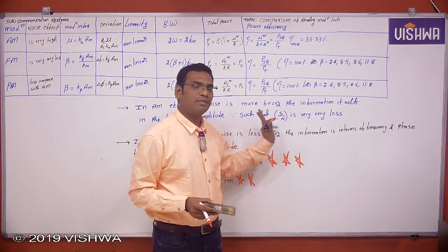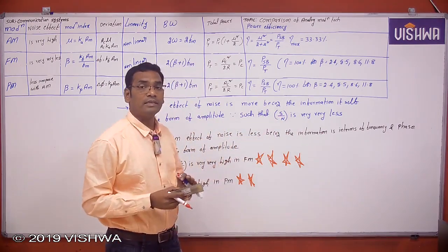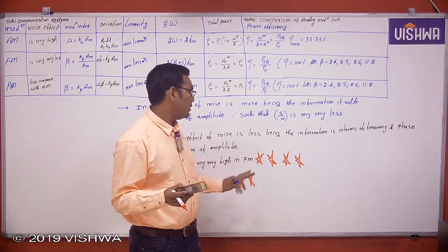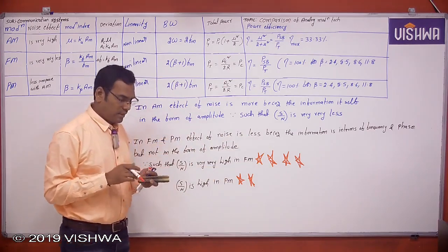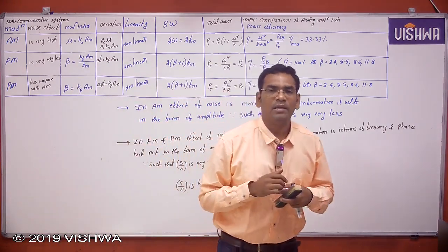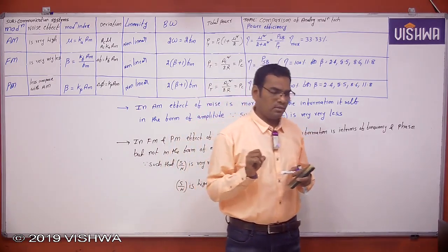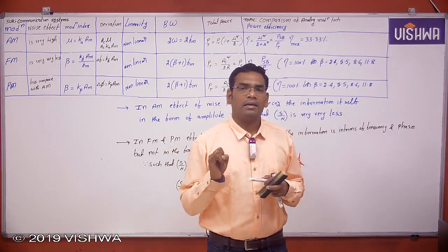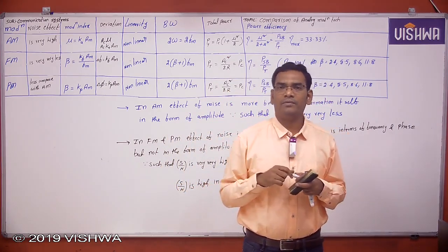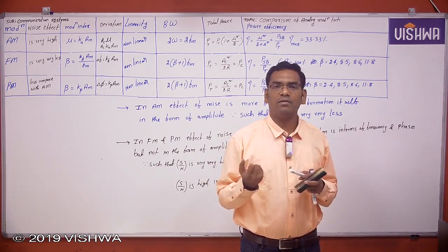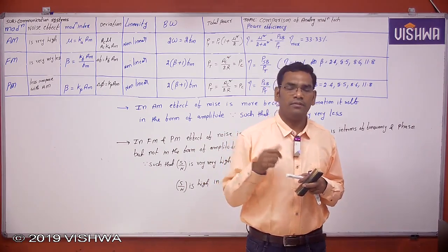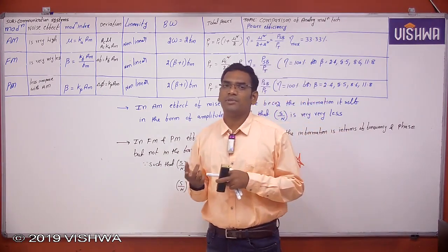Okay, between AM signal to noise ratio and FM signal to noise ratio there is a large gap, a large deviation. It is very, very high compared with AM. Therefore, we never prefer AM. That's why nowadays you are not listening to AM radio, you are listening to FM radio. So for audio signal transmission, FM and AM are preferred, but FM is the best one with respect to noise. Now in video signal transmission, VSB. For voice signal transmission, SSB.